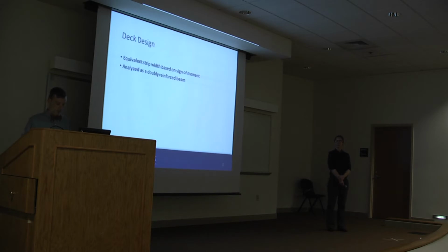We analyzed our deck as a doubly reinforced beam having top steel and bottom steel to meet the moment demand symmetrically. For our purposes, the compressive strength of all the concrete is 4 KSI.